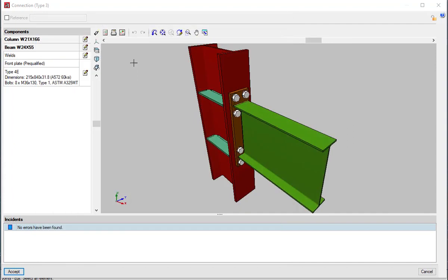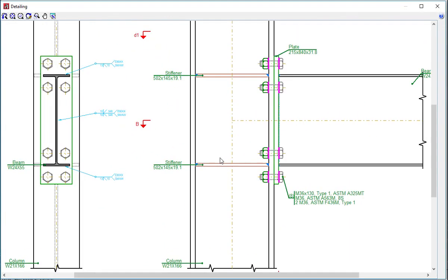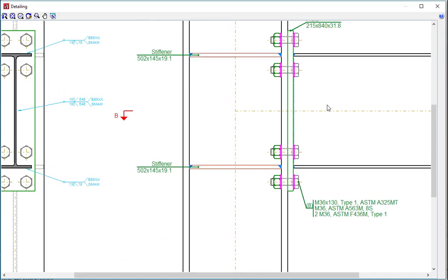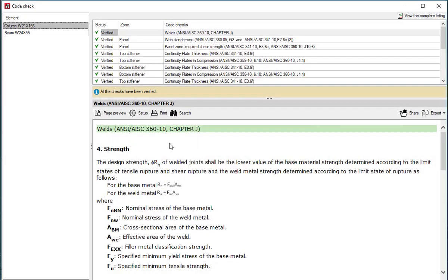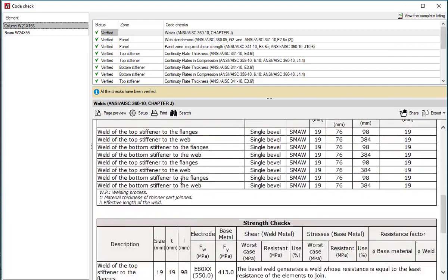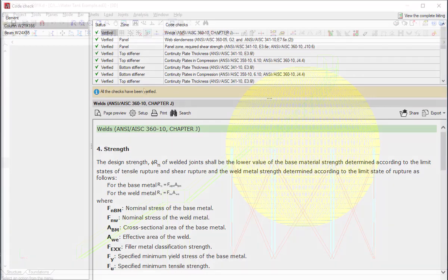After the joint design is completed, the program is able to provide the construction detailing for each joint, which includes a summarization of the properties in a detailed technical drawing. The program also provides a check report for each element against the according building code that was defined at the beginning of the project. The connections that meet the requirements will have a green check next to the code, and for those that don't, the check will show what needs to be changed.